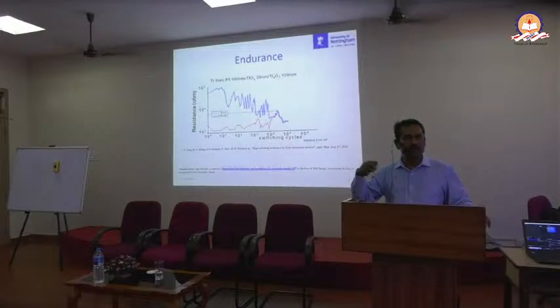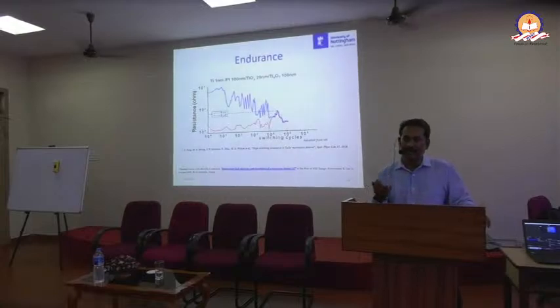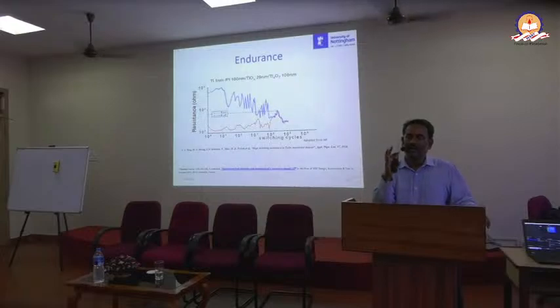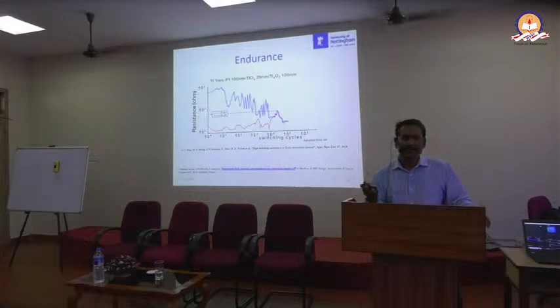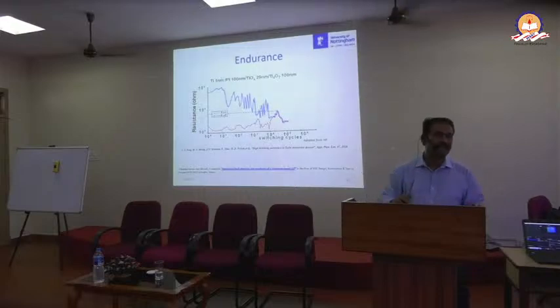There is a lot of research going on, a lot of materials they are using, and one of the interesting areas where they are using it is neuromorphic computing. Okay, you know about neuromorphic computing, right? Neuromorphic computing is computing that uses spikes. Can you imagine a CPU running without a clock? We need a clock signal to run, right? So Intel has released 2 processors, Loihi and Pohoiki. They don't use any clocks. They use all spikes, which is completely asynchronous.